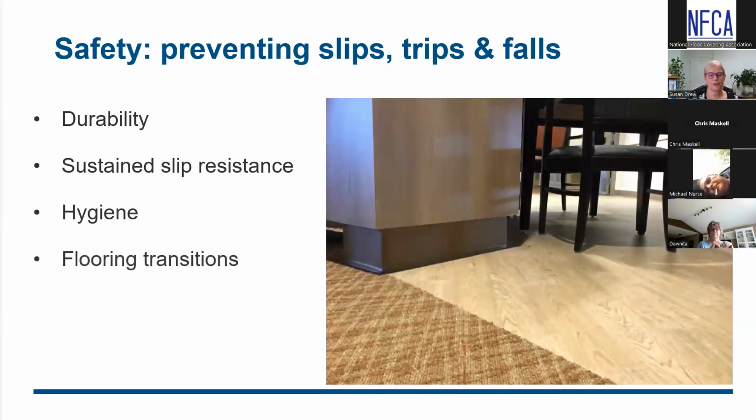And we want appropriate flooring transitions. We want properly selected and installed transitions, as these can be a huge tripping hazard if not handled correctly. And I'm going to assume that question earlier was what is considered a tripping hazard with regards to a transition. 1/8 of an inch, anything more proud than 1/8 of an inch is a tripping hazard.